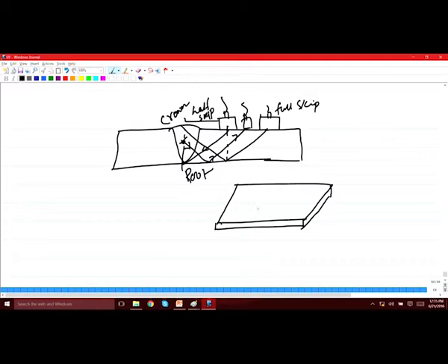So, let us say this is the weld that you have over here. Okay, so, this weld you are going to inspect, and you need to keep that probe first at the half skip. So, then it will go to the root, and then you have to move it to full skip as you do the inspection. Okay. So, for the entire weld you need to do this, you need to move in this fashion, you have to move from half to full and like this. Okay.